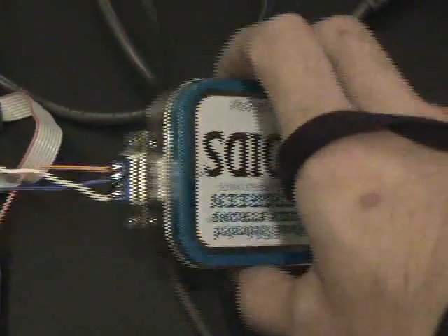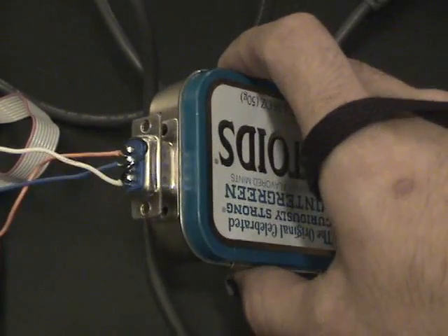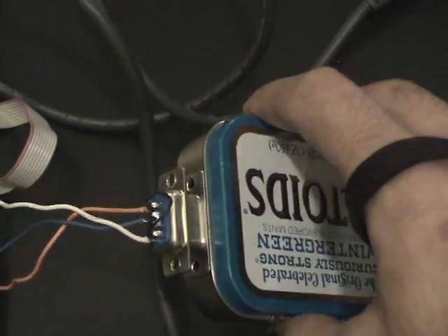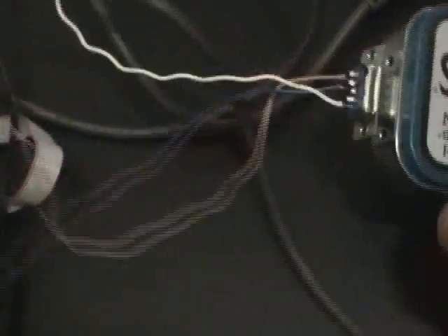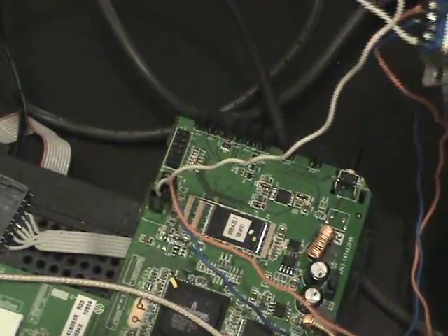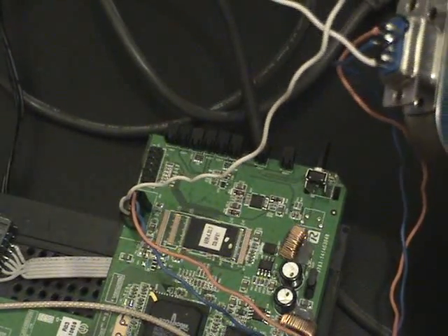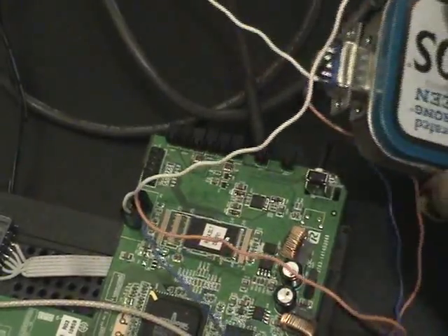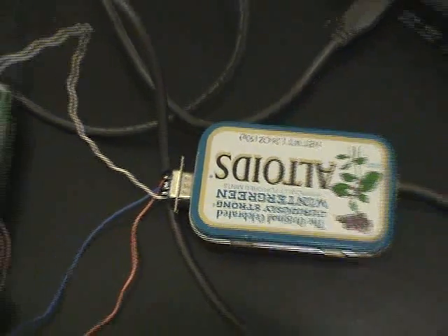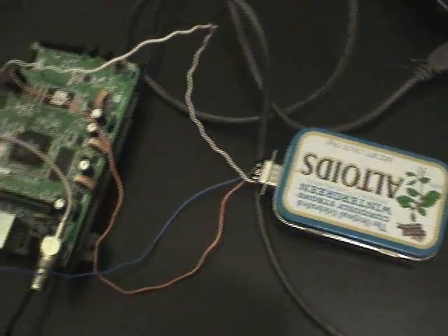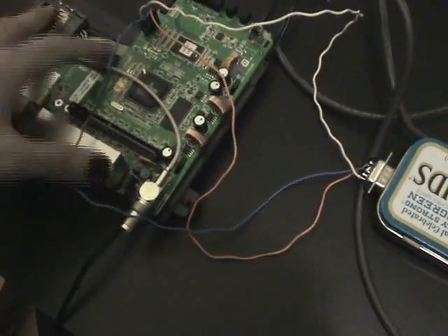Before we begin, the serial port adapter, 9-pin serial. This has been hooked up in the typical null modem 3-wire configuration and has just been jumpered to the board using the same type of jumpers I used on my MAX232 kit, which are the exact same jumpers that you find inside your PC for the LED and hard drive and all that jazz. So there's really nothing special to this. I'll just zoom out real quick and give you a quick idea of what we're working with. There's the level converter and the interface, and there's our WRT.